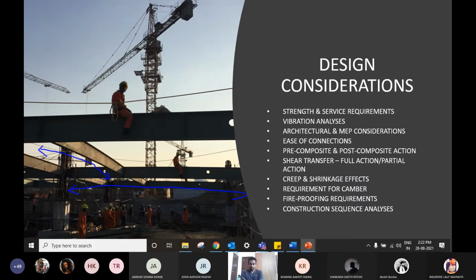So vibrational issues are typically the case: your member sizes, your beams, primary and secondary beams, the size in a composite structure like this is defined in most cases by vibration. In order to not have vibration, you need to increase the structural depth of these girders. So the structural depths are finalized not for strength design.